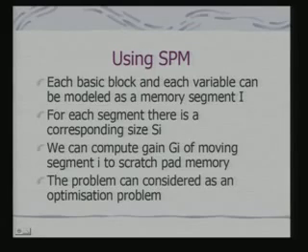After that, the problem becomes an optimization problem, because what you would like is to optimally exploit the SPM area to maximize the gain. So it is a pure optimization problem, just like a hardware software partitioning problem. In fact, this is a partitioning problem in the sense that you have got the code and you are trying to partition the code between main memory and SPM.